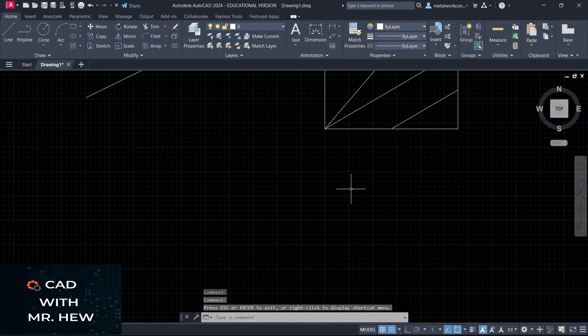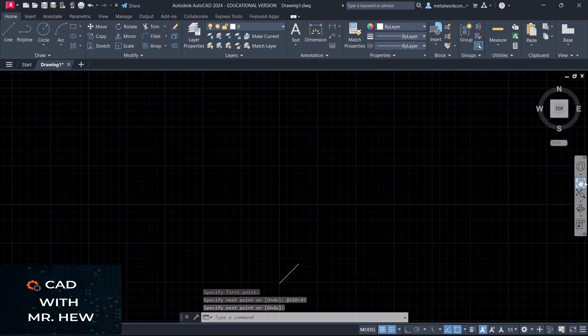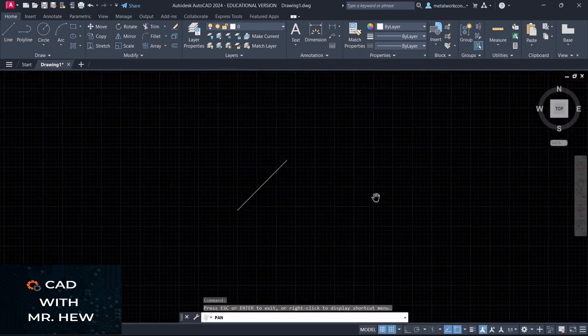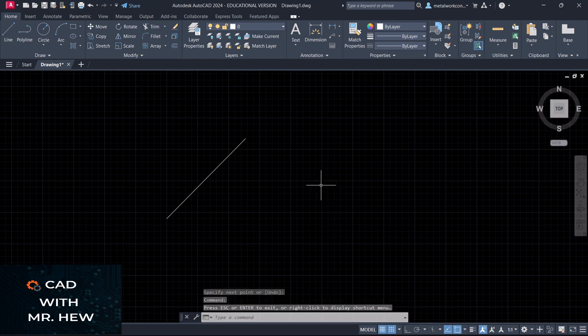All right. So the other way you can draw a line, you can go line, you click the starting position where it can be on the drawing or on a point on the grid. All right. So we click here, we're going to put at. So relative to this point, we want the line to be 180 millimeters. You're going to type the less than sign. That is how you would tell the angle, and then you can make it 45 degrees, press enter. Right? So if we press enter again, this is our line drawn where the length is 180 millimeters and the angle is 45 degrees.